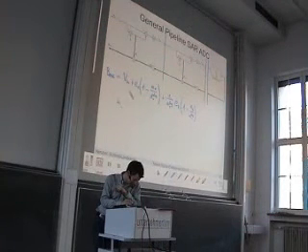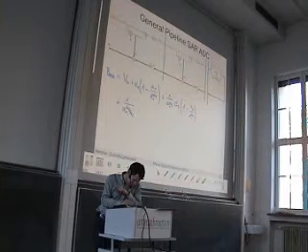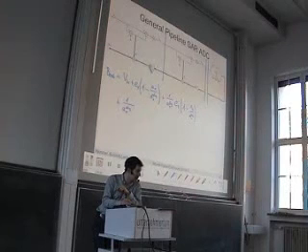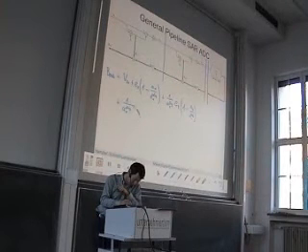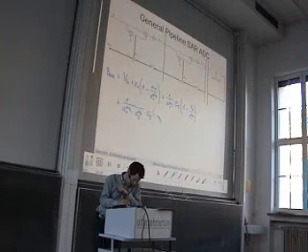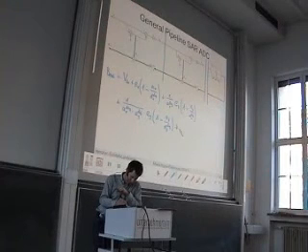I'll write it for the third stage again. Here we have 1 over A1 digital, which means that the quantization error of the first stage is scaled by this scaling factor. It is also scaled by this scaling factor. So we have here a 1 over A1 dig and A2 dig. Third quantization error times 1 minus A3 over A3 dig. And so on and so on.